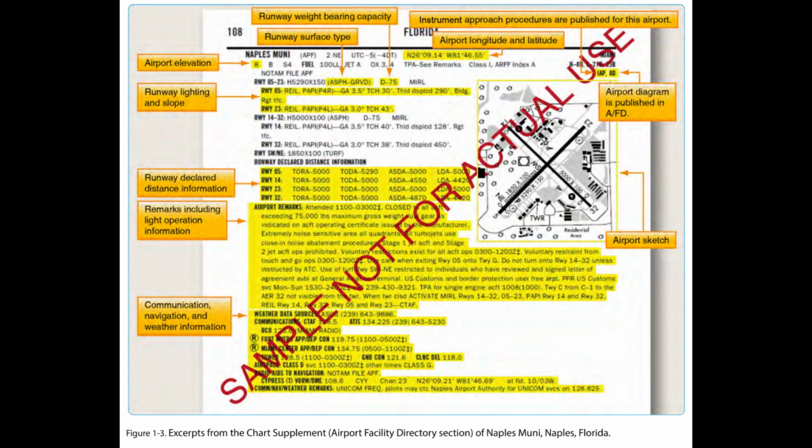The FAA requires the commissioning of an FAA-approved LVO/SMGCS operation for all new Category 3 ILS-supported runways. Since there are no regulatory takeoff minimums for 14 CFR Part 91 operations, the information provided by FAA AC 120-57 and FAA Order 8000.94 must be understood so that the general aviation pilot can understand LVO and SMGCS during day or night.